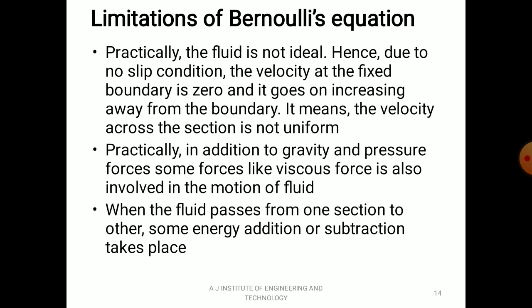Practically, in addition to gravity and pressure forces, some forces like viscous force are also involved in the motion of fluid. So because of viscosity of the fluid, we have to consider viscous force. So that is the case here. We only consider pressure and gravity force. So in addition to pressure and gravity force, there comes into picture the viscous force. When the fluid passes from one section to another, some energy addition or subtraction takes place. About this we are going to study in laminar and turbulent flow as well as in minor and major head losses. So because of the flow from one section to another section, that may be section 1 to 2, we may have some energy addition or subtraction inside the system.